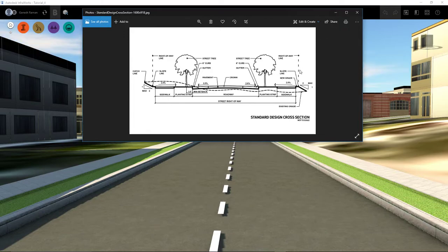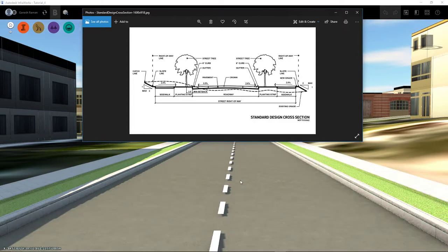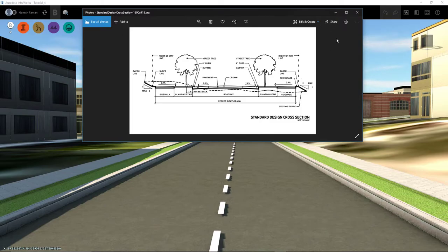The points between the lanes or to the ends of the lanes that are used by the city to lay the road is called the right-of-way line. And the components of the road are contained inside the right-of-way line. So they have curbs, gutters, sidewalks, medians, shoulders, roadway transitions, plants, street lights, all these things. So we are interested in creating something similar to this for our project to connect between Austin and Jocelyn.